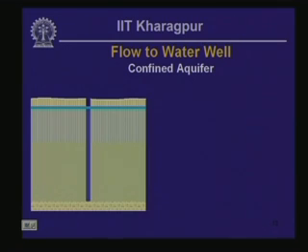Okay. So, if it is a sub-artesian confined aquifer, then the water level is going to rise to a level below the ground surface, as is the case on this particular section shown here. If it is on the other hand an artesian water well, then the water level is going to rise above the ground surface.